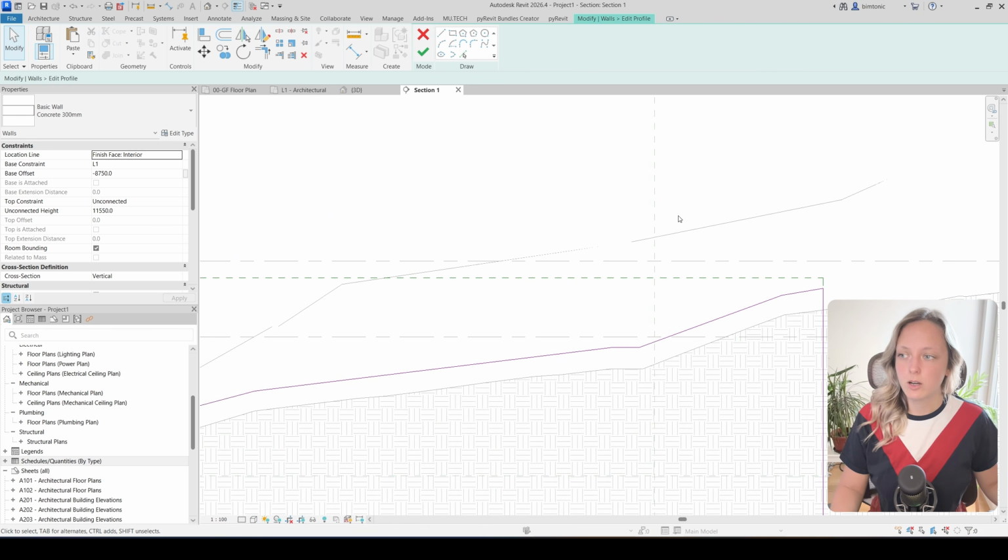So essentially, if we are going to be taking the footing that is 400 millimeters thick and our minimal depth of that bottom of the footing is 900 millimeters, that means we are going to have to offset the bottom at least 500 millimeters. Of course, I don't want to be within these minimal values. I do want to actually go a little bit above the minimal values. So I'm going to take, for example, 700 millimeters. Of course, like I said before, don't take these values to mean anything. This is very related to the type of soil, to the country you live in, to the regulations, etc.